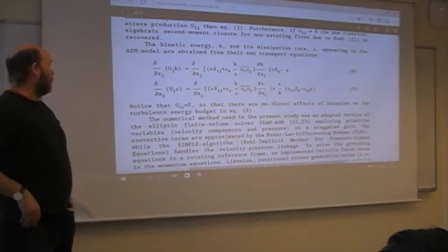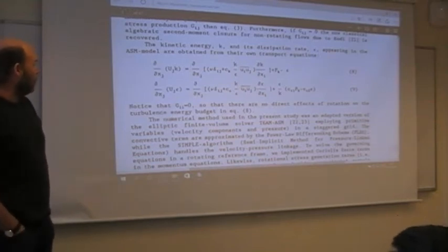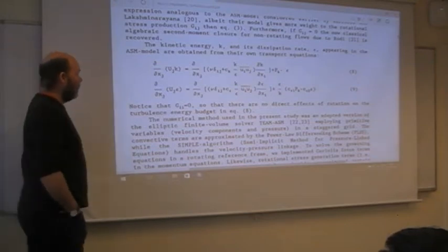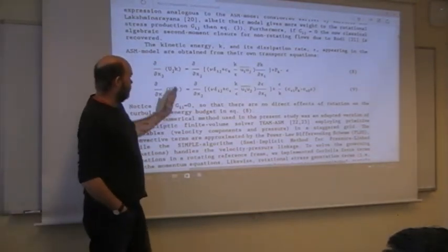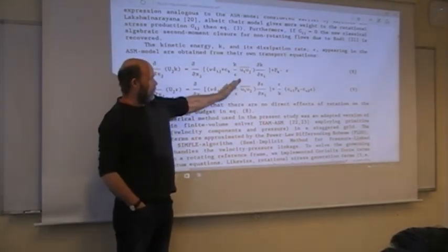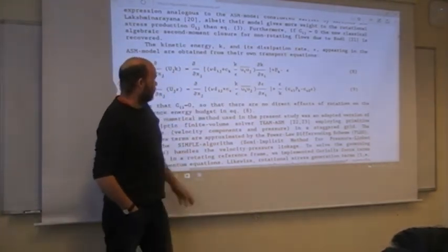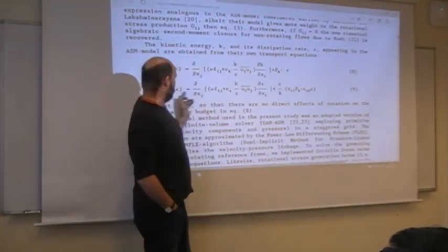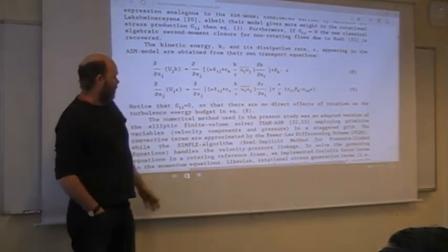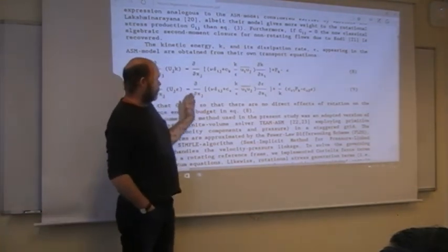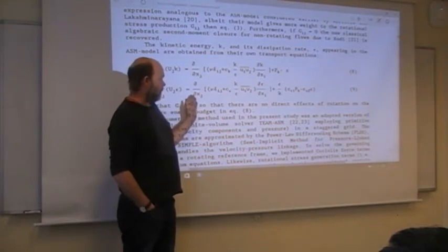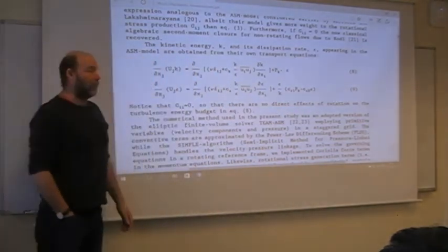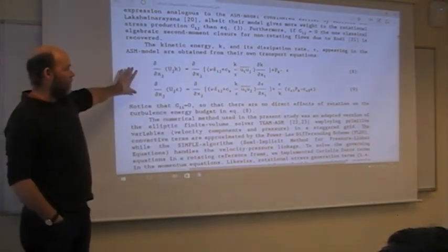So here are the K epsilon equations. And as you see, it's mostly a model on the other side. The production term we can sort of work around. Dissipation has its own transport equation. And here, production term, diffusion term, and also the dissipation of the dissipation. Everything has to be modeled, so you can't use the exact equations, no way.